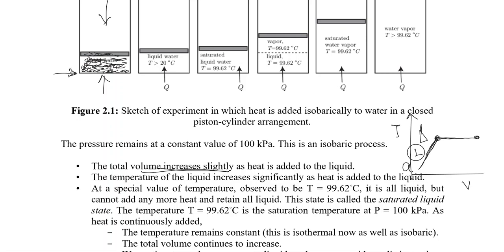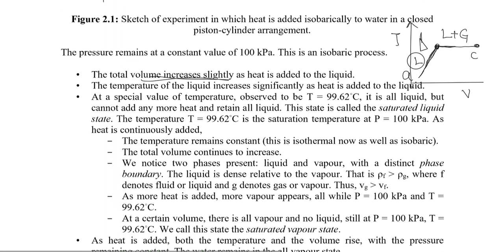so from B to C, there would be liquid particles somewhere over here. That liquid would start absorbing heat, and it will be converted into vapor. So from B to C, there will be a phase transformation from liquid to gas. But inside this B to C, there is a two-phase mixture. That means we have a liquid as well as a gas. So the temperature would remain constant.